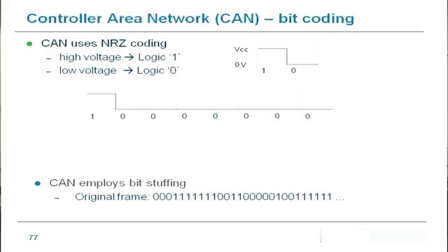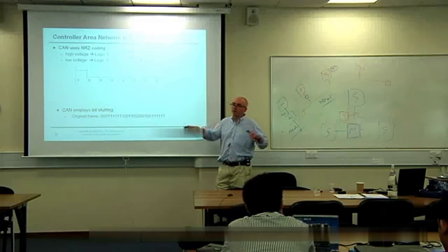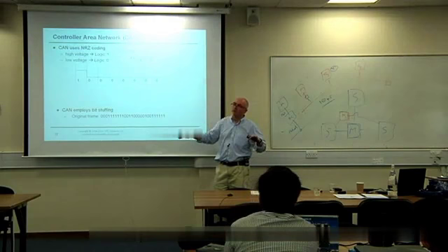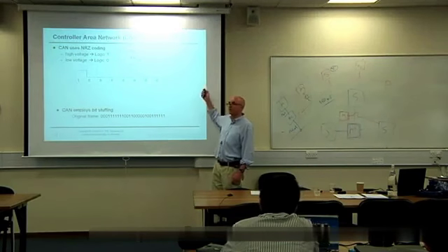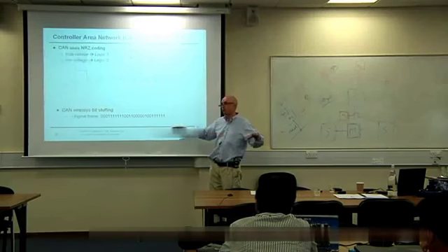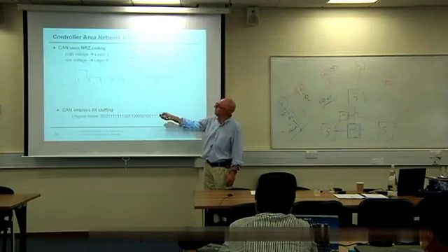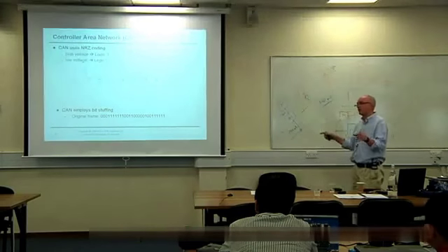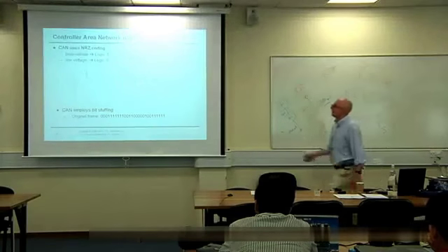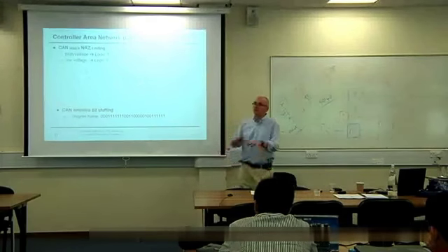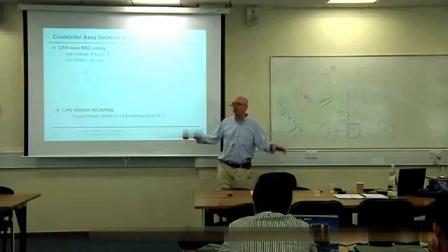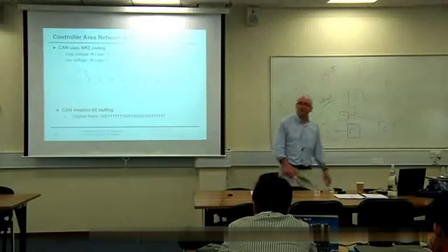At the lowest level, if CAN was to send out a long stream of zeros, there comes a point where the clocks in the actual CAN hardware would have drifted enough for it not to be able to pick up. When that eventually goes back to 1 half an hour later, by that stage the clocks will have drifted. What the system does is it uses periodic flips between high and low level to synchronize internally the hardware that's used to actually measure whether that's a 1 or a 0. Obviously that has to be synchronized because it should be checking in the middle of each bit each time. And to do that, it has to have an internal clock that's synchronized to the message transmissions.